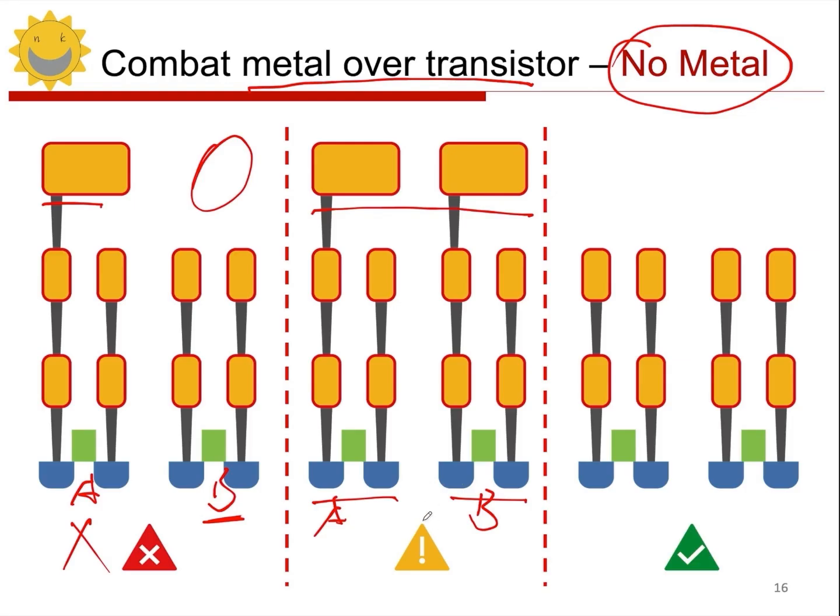However, this situation also requires a lot of caution, right? Even though A and B are the same, both A and B will be affected, meaning the impact of this hydrogen annealing process means that both A and B will show some deviations in their characteristics. Although the degree of deviation is the same, the characteristics of both A and B will deteriorate. So about this, you need to be very careful, very careful. This method should only be used in situations where space is extremely tight, right?